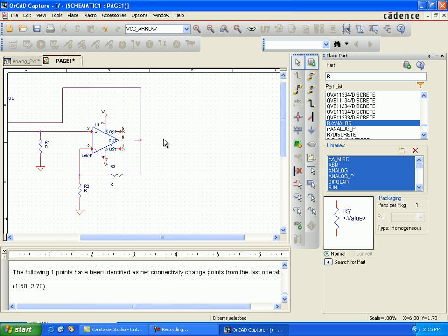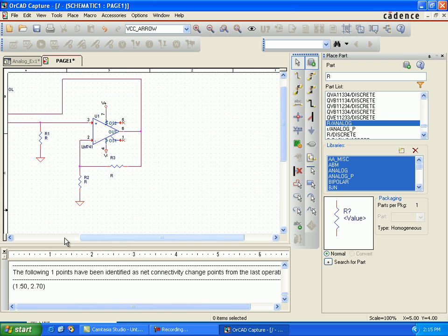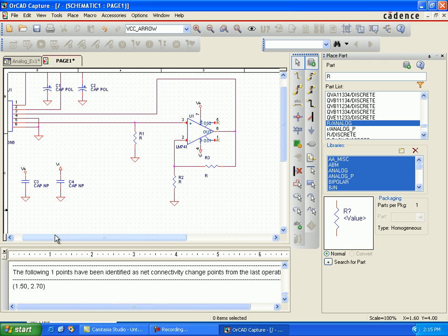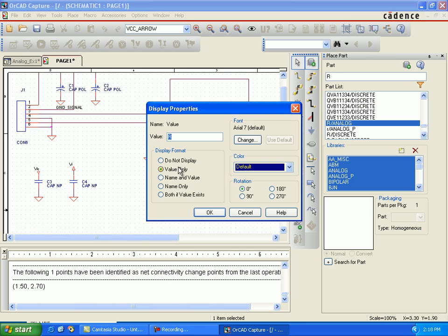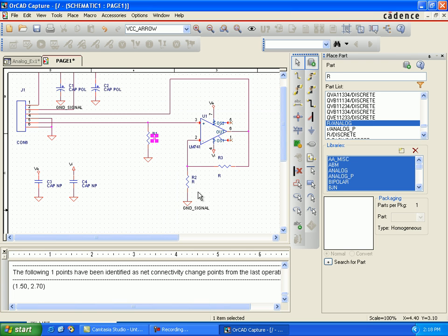Make sure that all the components are connected well. Please zoom in. The op-amp has 2 pins for input and output. It is giving input at the positive terminal, pin 3, so whatever input will be positive, not inverted.